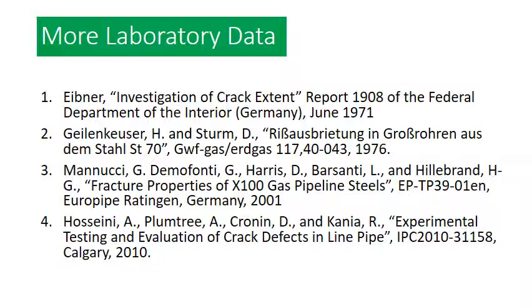Now, some of you that are in the business will probably look at this list and ask me where is the Keller data and where is the Reyna and Rawls data and things like that. I know that there is other data available that could potentially be used, but my feeling is that those data sets are not appropriate because they're not using pipeline steels. They're using various heavily alloyed steels that are used for pressure vessel situations.